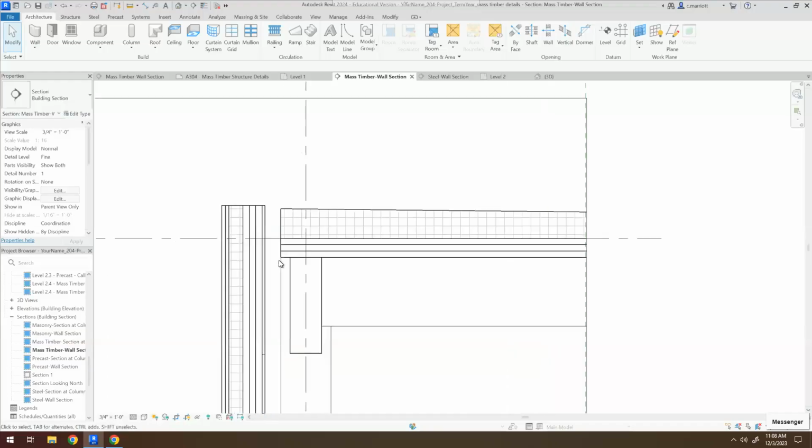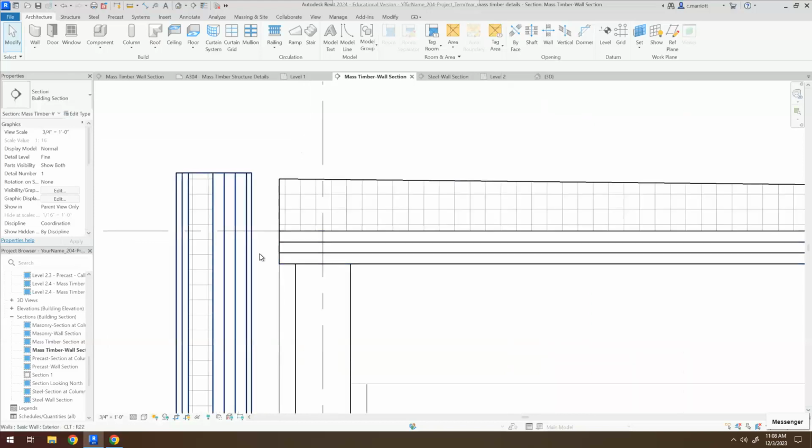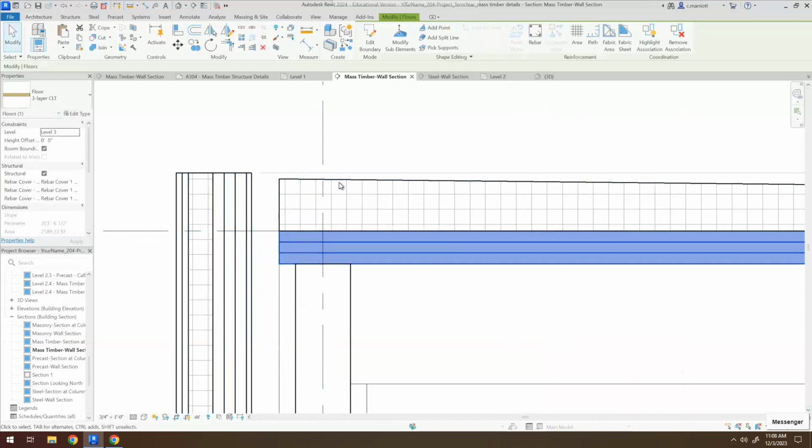Okay, now what I want to do is bring out the roof and the insulation layer here. Right now it is measuring 5 3/8 of an inch from the column line, and I want to bring it out to 1 foot, 1.5 inches so that it goes this far. So I need to bring it out 8 1/8 of an inch. So I'm going to click on it.